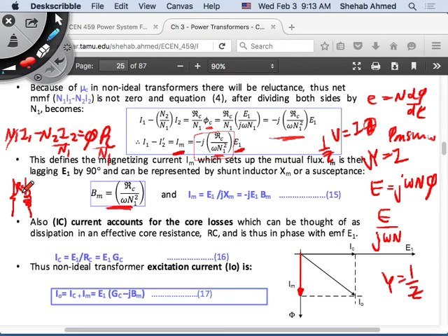The current flowing through it is going to be 90 degrees ahead of the current flowing through the magnetizing inductance. It's going to be in phase with the voltage that created it, which is the primary voltage. I think that's what we're going to be calculating next. So we calculated the reactive component, and the magnetizing current is equal to either E over jXM or minus j times E times BM.